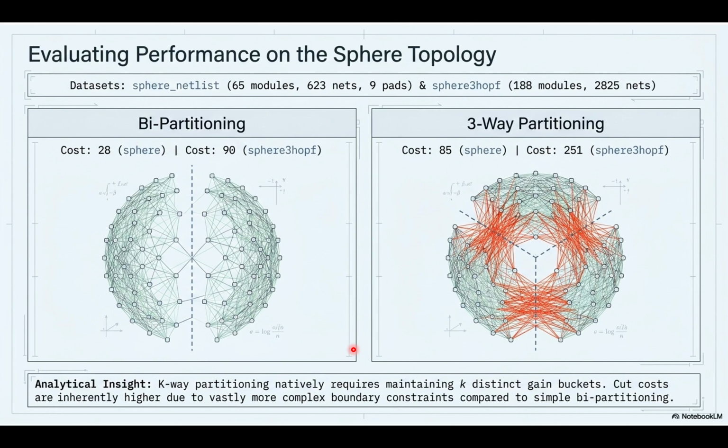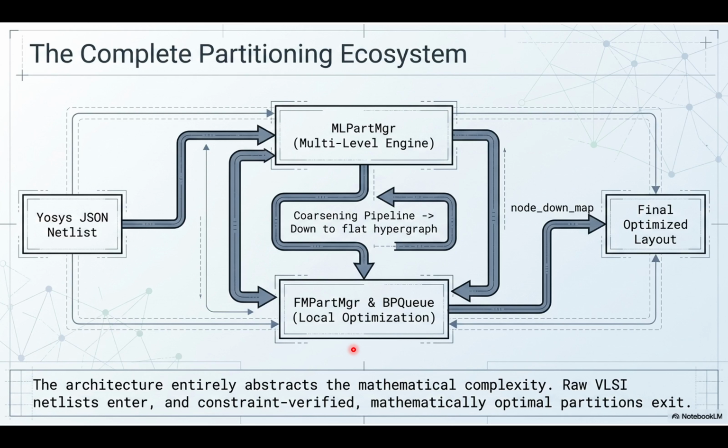optimization. Wow. And it highlights exactly why multi-level coarsening is so critical. If you can encapsulate those dense logic clusters into supernodes before applying the K-way constraints, you physically prevent the algorithm from driving a hyperplane through them. Because they're already locked together as a single node.